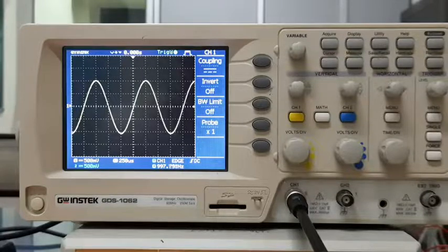If it's at channel 2, then set the parameters for channel 2 accordingly. What parameters? The amplitude scale or the volts per division. Set them so that you can see the full signal inside the vertical window. The time scale, so that you see at least a couple of cycles of the signal inside the horizontal window, and set the trigger level to the correct input channel and to the correct value.